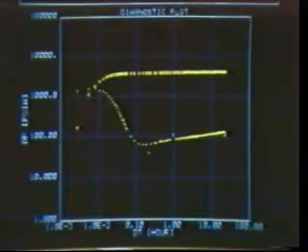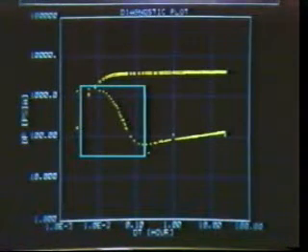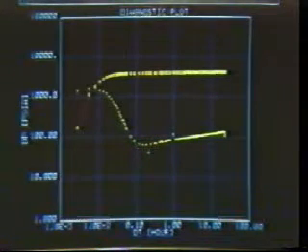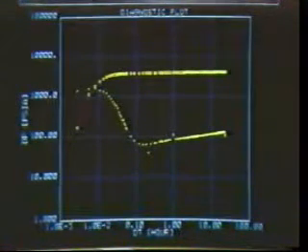The derivative plot is especially useful when trying to determine the end of the wellbore influence period. Note the characteristic hump in the derivative values, followed by a flattening. The end of wellbore storage is sometimes evident on the data plot as well, but it can be more readily and accurately seen on the derivative plot.